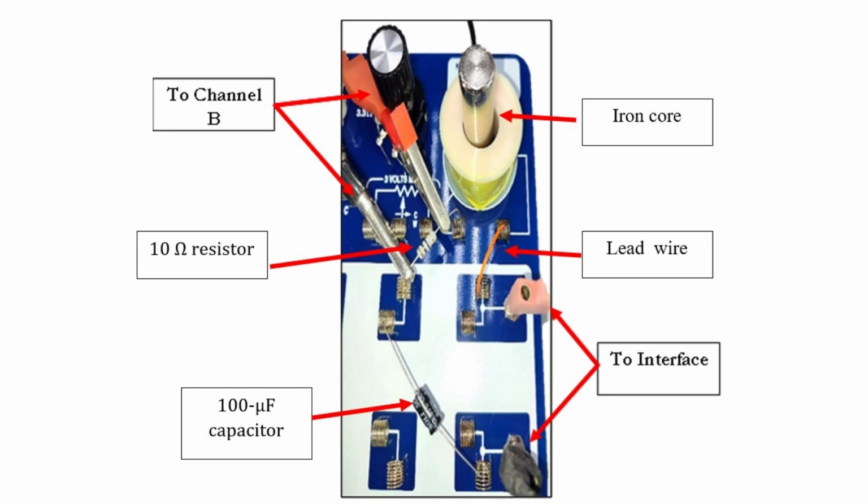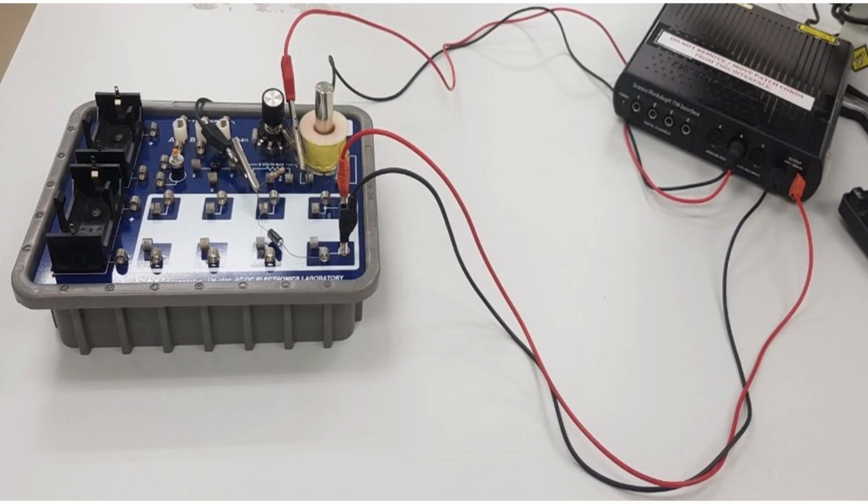The voltage measured at analog channel B is related to the current through the resistor by equation 12.4. Current I is equal to the voltage across the resistor divided by the resistance. 5. Connect banana plug patch cords from the banana jacks on the edge of the AC/DC Electronics Lab board to the output ports on the Science Workshop interface. The completed connection is shown in Figure 12.4.